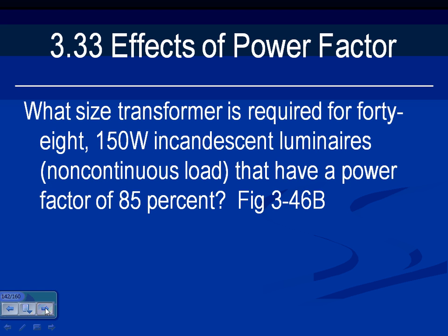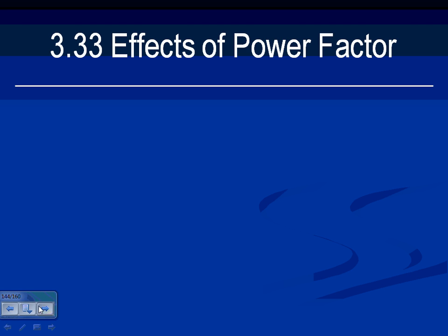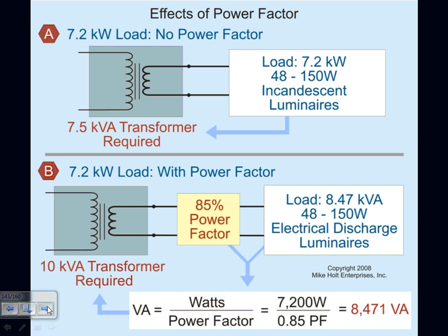Effective power factor and sizing transformers. So this is really just to drive the idea that you have to size your transformer based on the power factor. So as I said, now if you look, do I need a transformer of 72 kilowatt? If you say kilowatt transformer, everybody knows that you've never been in the electrical industry.